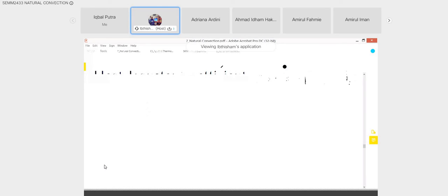What you are going to use is this equation. You are going to use this long equation to calculate your Nusselt number. Both regions are valid for this one, but it's a bit long and complex, but more accurate. You can use this one, no problem. If this falls under this category, you can also use this one. If you calculate your Rayleigh number in this region but use this one, it is also correct. It is complex but more accurate, and the other is still acceptable.